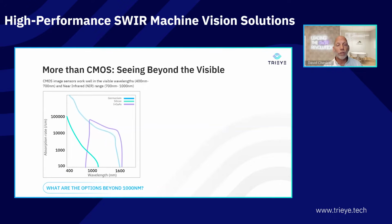That's why we're exploring new technologies like germanium. Germanium is shown on this curve here. It works well in the visible spectrum, but it works really, really well also in the SWIR spectrum between 1 micron and 1.6 micron, where InGaAs works well also, but CMOS doesn't work at all.